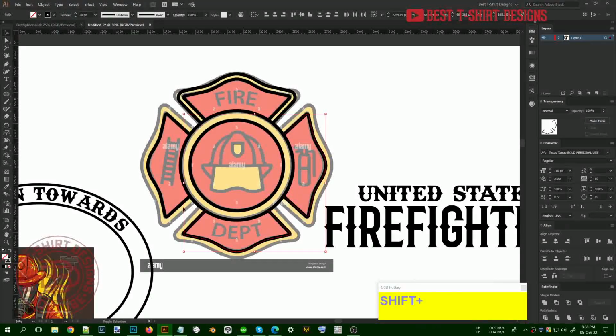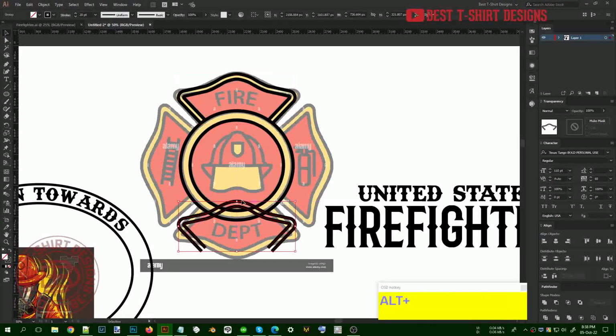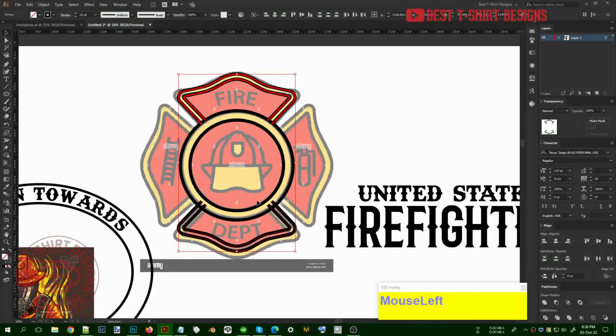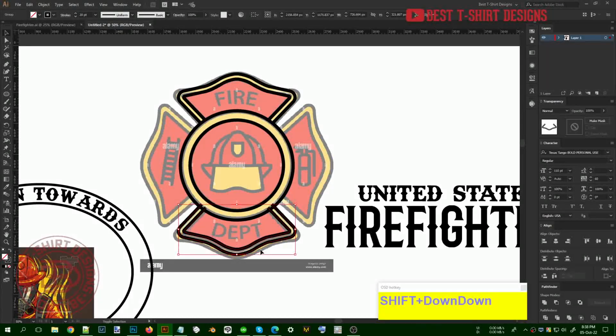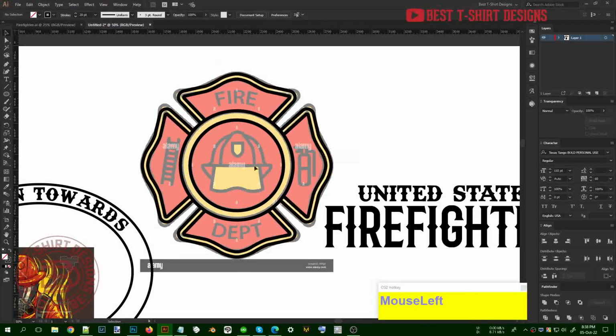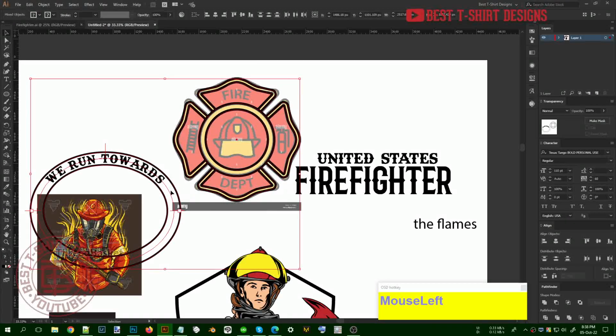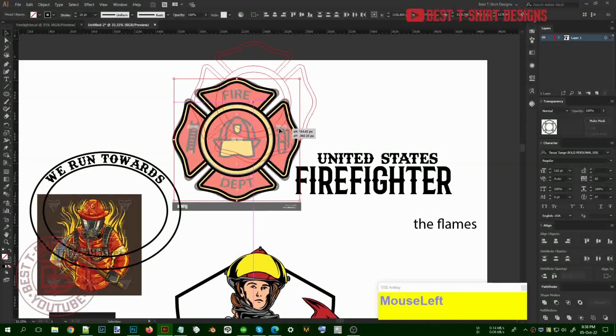So let's just do it one more time. Sorry guys. So let's make it a group. I'm going to bring it here, change the direction, make sure to align it with the top one. And once you are satisfied with this position, let's just select this, Ctrl C, Ctrl F. That means copy paste in front, and then just rotate the direction. So this is good. Now this is going to be the shape I will be using.